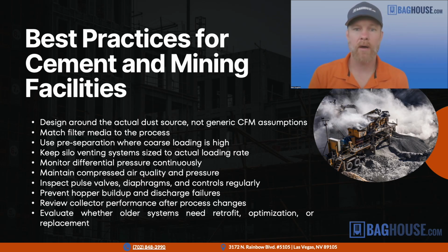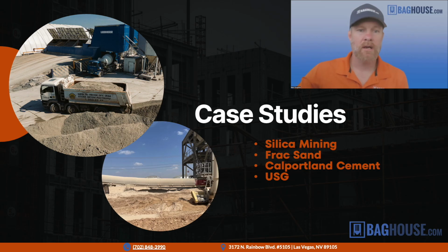And then, we talked about the maintenance and inspection requirements, putting in proper maintenance checklists and so forth to make sure your pulse valves, your diaphragms, your controls, your compressed air, their filter condition, all of those components are properly maintained so that you have a good dust collection system that will work for decades and give you the performance you want. All right, so in the next slide here, we're going to talk about a couple of case studies.